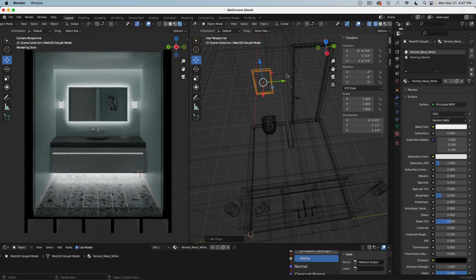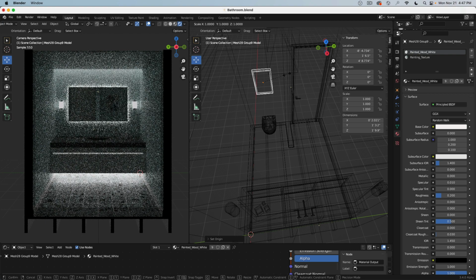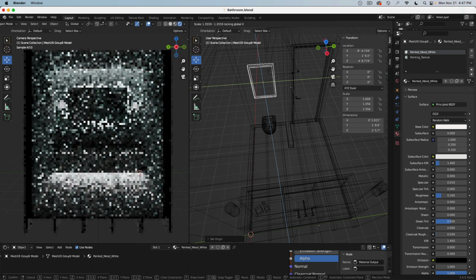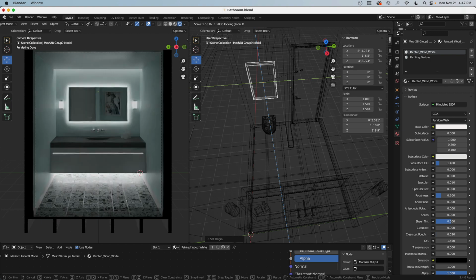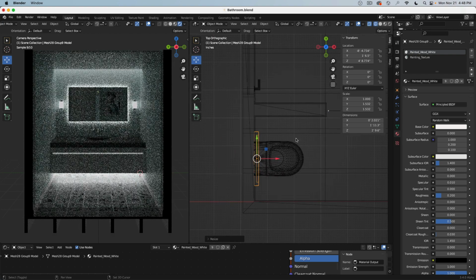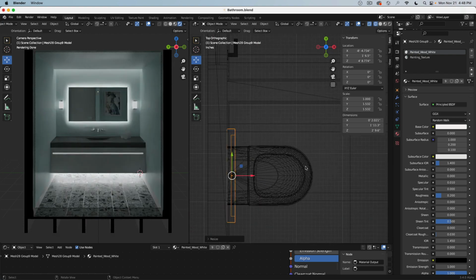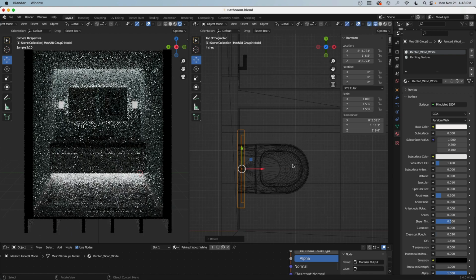And then when I press S and Shift X in my case, it will scale it up and left and right, but it does not scale along the x-axis. So when I take a look from the top, you see this does not get thicker. S and X scales along the X, Shift X, it scales along Y and Z.